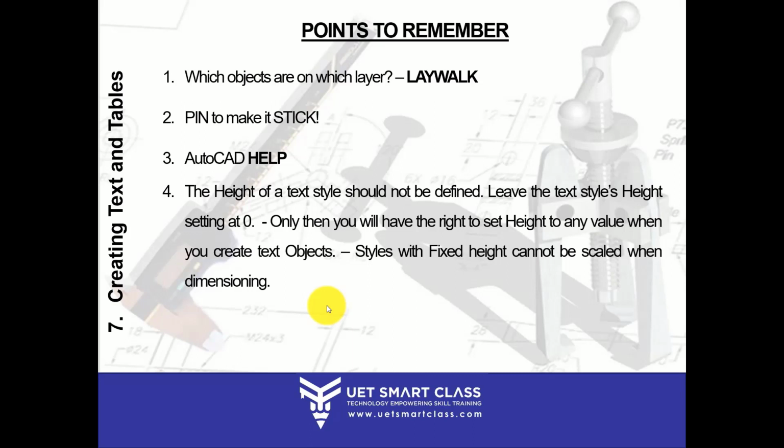Using a style with fixed height is like, I would say, throwing a monkey wrench into the dimension machine. Just imagine. What will happen? A big crash and then boom, blast. But still, if you like to live on the edge, you can go ahead and fix the style of your choice. But in that case also, I would just want to say, fix the text style height only when you do not want to scale it when you're doing your dimensioning.